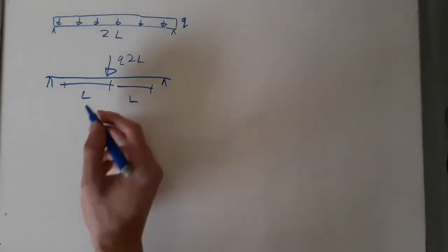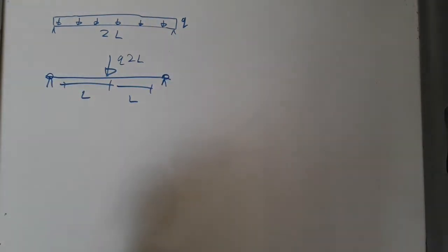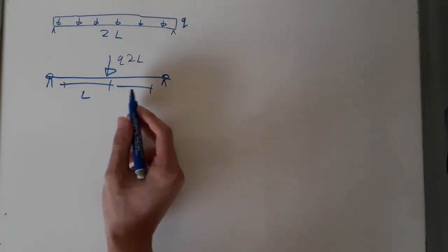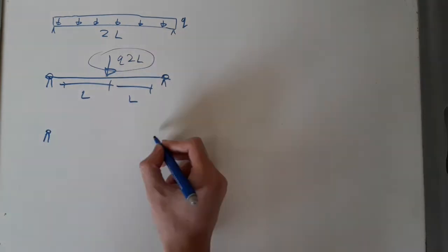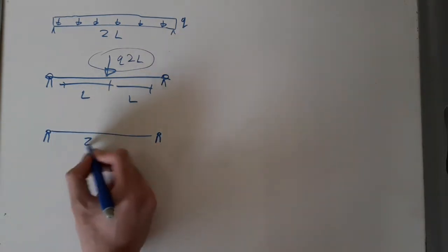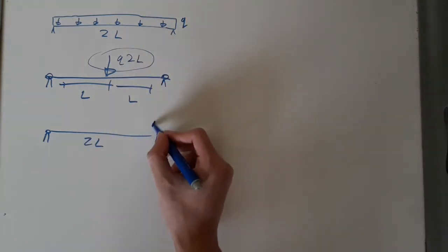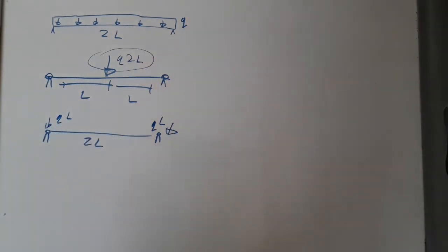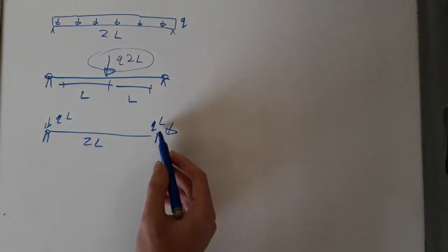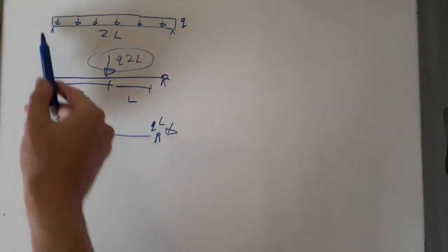But now obviously, if we're doing finite element methods, we only have nodes here and here, and we want the forces at the nodes specifically. So to do that, we would just take this equivalent load and divide it between the two nodes. We would have the two nodes here, the length 2L, and this force divided by 2 at each node. So it would simply be QL here and QL here. That would be the simplest scenario of a work equivalent load, because these two nodal loads represent this load here, which would represent this entire distributed loading.